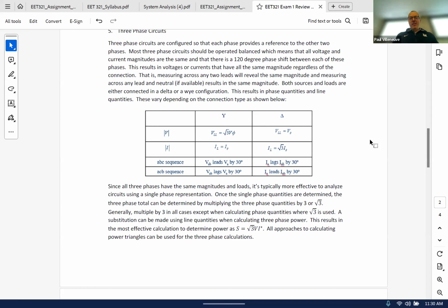And then hopefully what you've been seeing, if you've been doing the bonus transformer problem for the test, you actually see where you have to keep track of the power, because those are 3-phase powers. You have to do some conversions to get single phase equivalents.